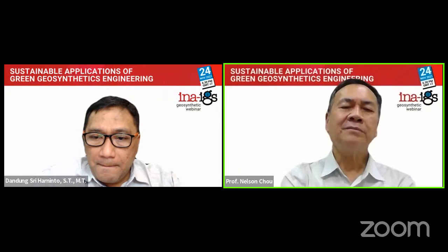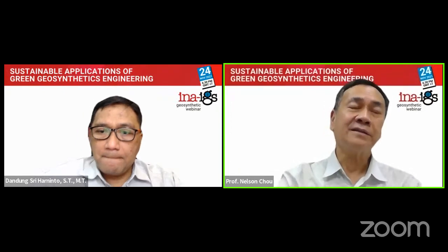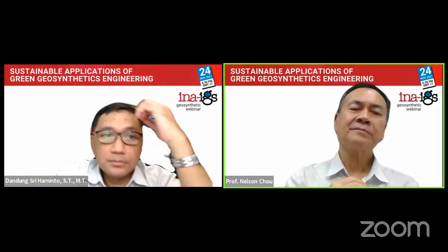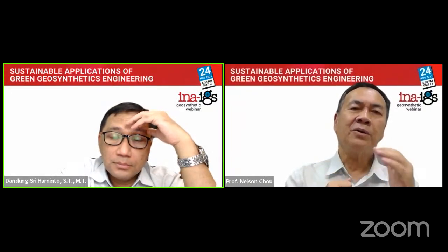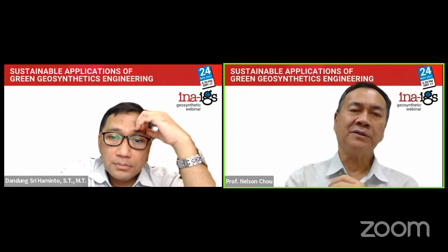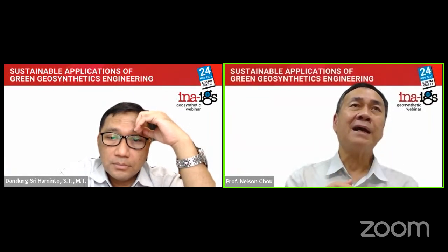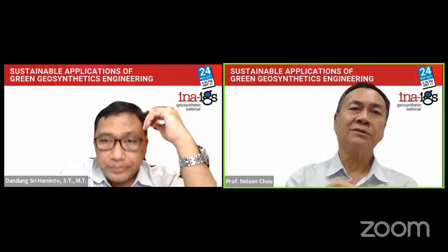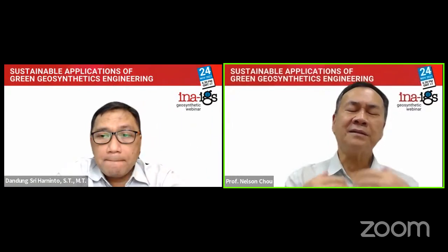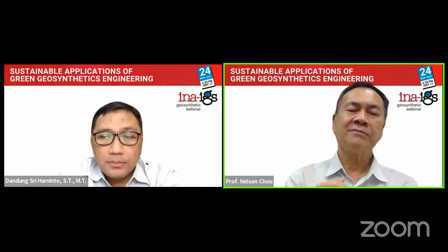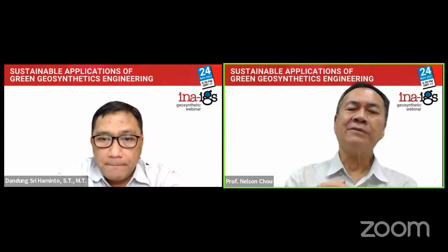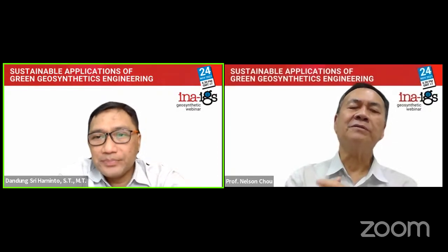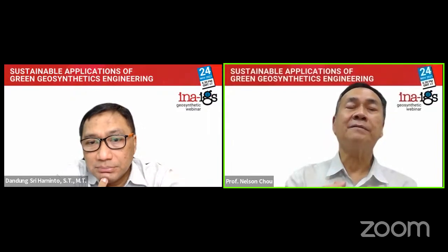But Geotube, usually we put in layers. The lower layer is covered by the upper layer. The upper layer, we also cover with some material, probably soil material. And we use vegetation on top of the soil. So it's not really subject to sunshine. Once covered, it can last for a long time. The material itself is a geotextile.